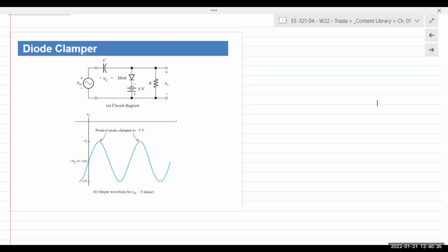Yep. Tau is equal to RC, the time constant for an RC circuit. Anyone remember it for the inductor? Anyway, coming back to our circuit. Capacitor right here connected to a diode circuit in conjunction with a battery. Positive half cycle, what happens? Diode gets forward biased, capacitor charges up, circuit current is actually flowing in this direction.